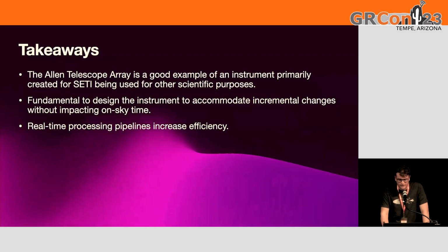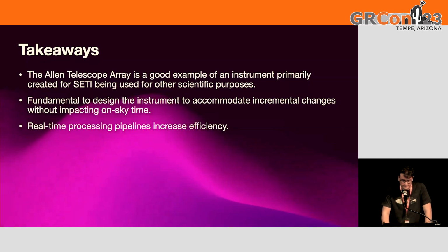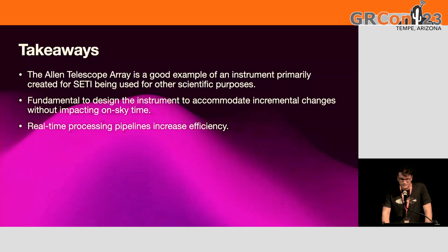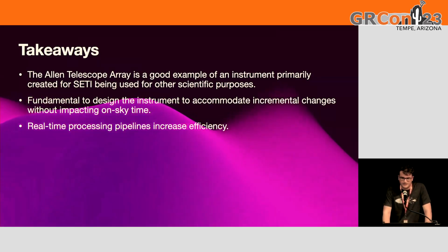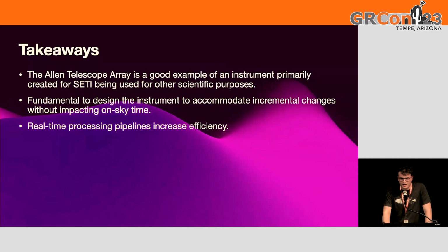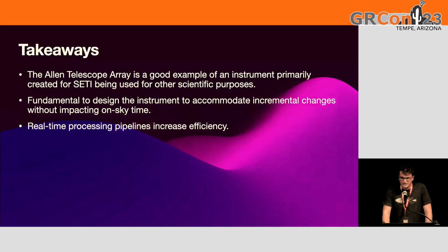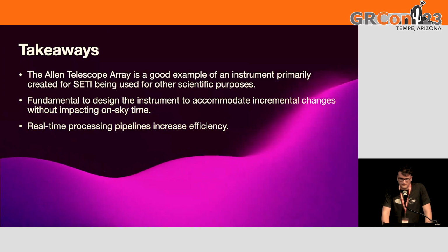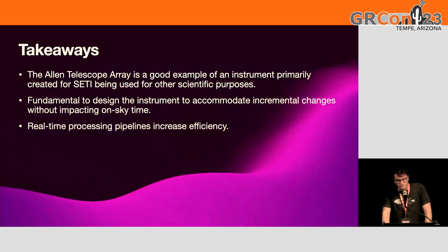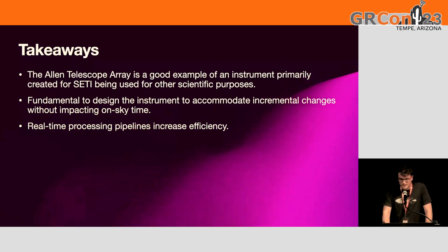And also, real-time processing will increase your efficiency, because if you think about this, if you are saving the data you are producing, you need to write that to your NVMe storage, and that write will pass through PCIe, and then you have the bottleneck of the NVMe itself. And then when you need to read that again, you need to do the opposite. So you're trying to read through PCIe again.